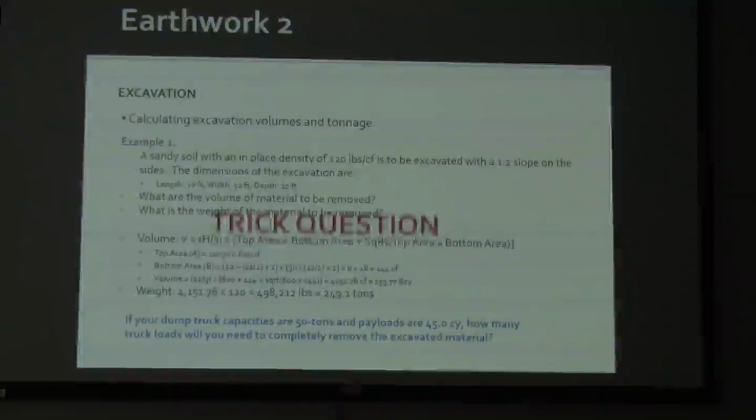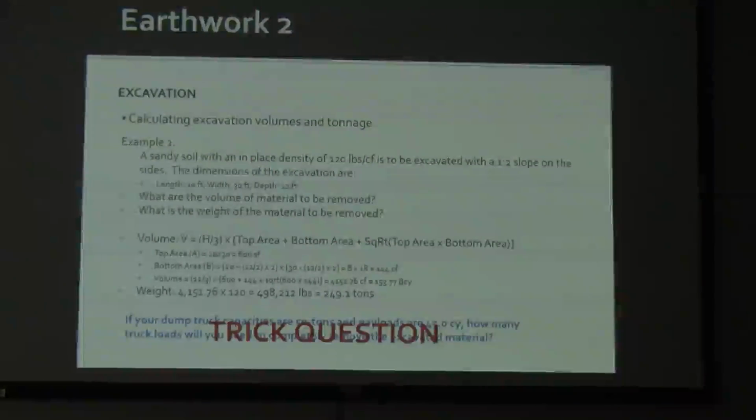Well, the truth is that it's a trick question. And why is it a trick question? Because we only know what the bank cubic yards are. After we excavate material, it becomes loose and its density goes way down because it's a looser material. So our volume goes up. The weight stays the same of our total excavation.